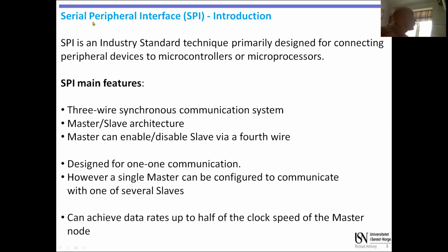So we start with serial peripheral interface, and it is designed to be for connecting peripheral devices to microcontrollers or to microprocessors. So it's specifically designed, look at the name of it, serial peripheral interface. This is a communication system that is much more modern than simply USARTs and is designed specifically for connecting these kind of devices together.